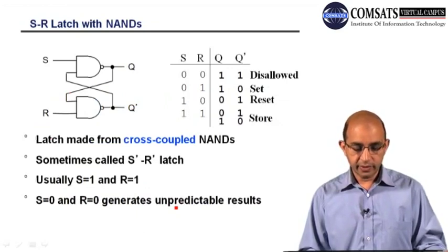Okay, so that's the SR latch with NAND gate, although you have already seen the latch with the NAND gate. Here we have the summary of the SR latch with NAND gate. Here you have the NAND gate, and this is the output, and that is feedback, and this is also the feedback. This is the function table of SR, mentioning the functionality: S R Q and Q bar, 0 0, this is 1 1.